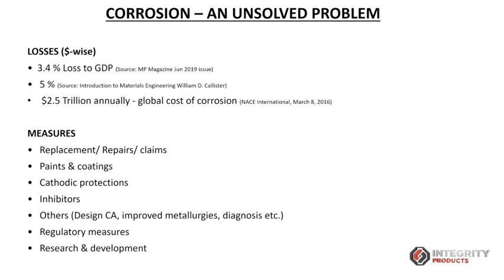And also there are certain measures in terms of paints and coatings, and definitely it's a huge industry. There is a huge investment in cathodic protection and corrosion inhibitors. And also, at the time we design the equipment or the vessels or the lines, we always over-design them. We keep the factor of safety, we keep the corrosion allowance in that. We try to go with the high metallurgy, high-grade alloys with the improved metallurgy. And we spend money on all those measures.